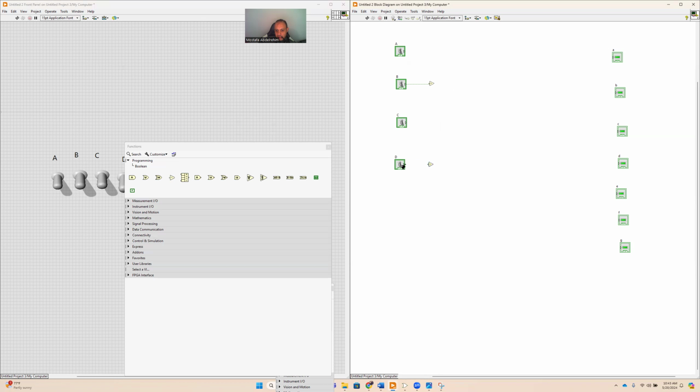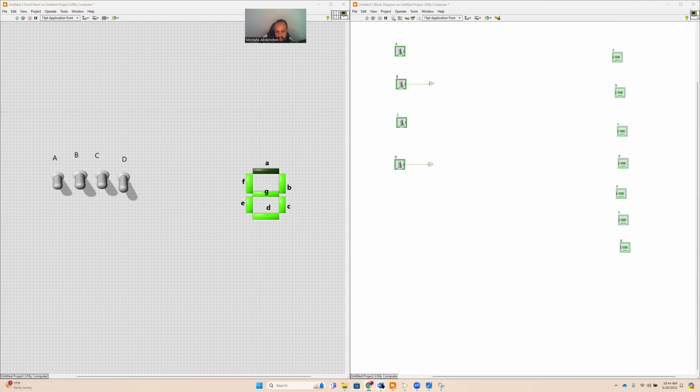To connect, you see this dot here. It will appear when you hover over it. Once you hover over it, a link activation will happen, so you can create a link. Okay, so we have B bar, D bar now. So we need to AND B bar, D bar. So if we go back here, we need an AND gate between B bar and D bar.